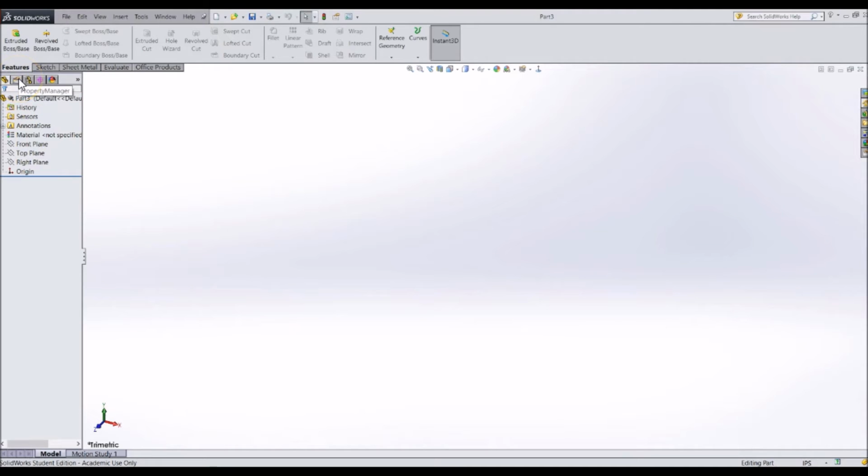In the second tab in this window, we have the part properties. This will populate with all of your file's properties. This next is used to create configurations of a part or assembly. You can also change the display state of your file. Finally is the Appearance tab, where you can see the colors and appearances of your part, along with the decals you've used and your scene. These are not usually adjusted, unless you are creating a render.